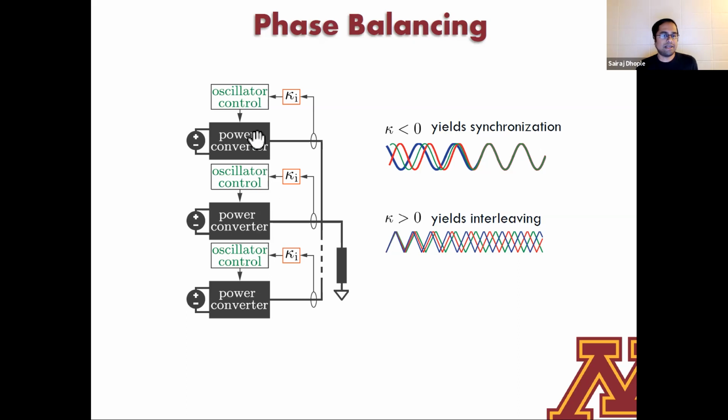The idea is the same: you have power converters that are all connected in parallel. I'm not going to tell you whether they are AC or DC waveforms, but you can see where I'm heading. I'm closing the loop with a gain, and this oscillator control is what we talked about earlier. You can utilize many different types of oscillator dynamics as well. And it just so turns out that the sign of the feedback here is super important in terms of realizing one type of behavior or the other.